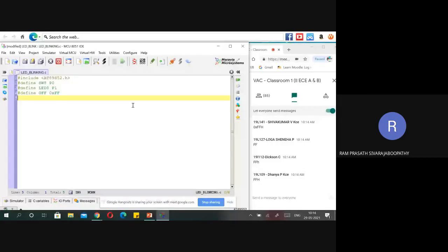One large we have to write. Of course, here we are dealing with an 8-bit device. So 0xFF. Very good. Thank you. Okay. Fine. Then to configure all the port pins at P0 as input, what about the data we have to use? Yes, input. So for that also we have to use 0xFF.